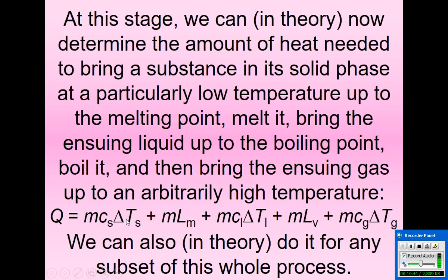And then, of course, ΔT depends upon where we actually start. The ΔT_S is from the initial temperature of the solid to the melting point. The ΔT_L that we see in this full-length formula is from the melting point to the boiling point. And then the ΔT that we see for the gaseous part is from the boiling point to whatever desired final temperature.